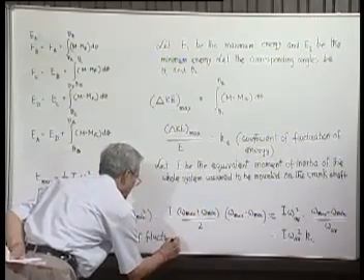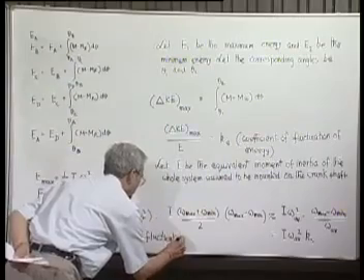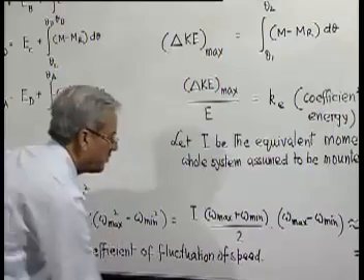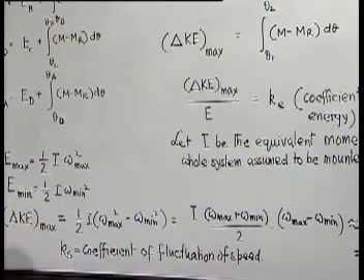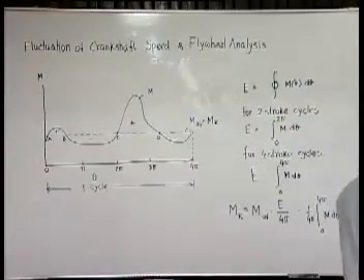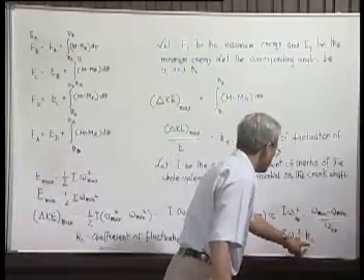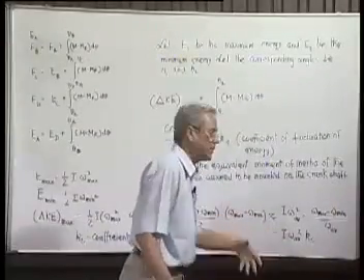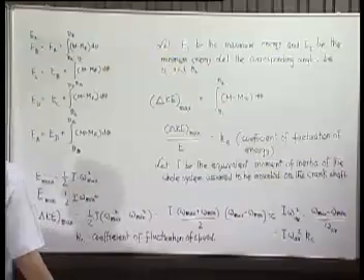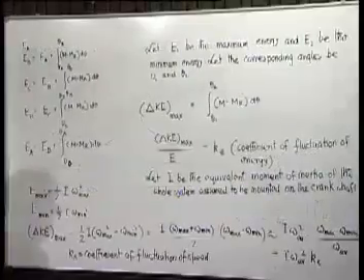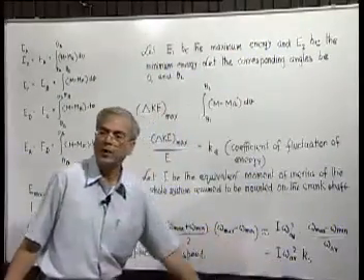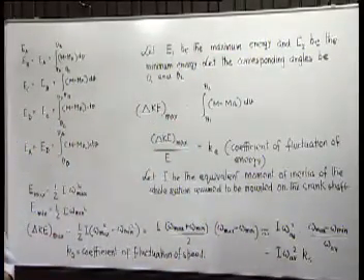This is an important parameter which has to be prescribed depending on the situation or the kind of machine we are driving with the engine. So therefore, we find that if Ks is prescribed, running speed is known, which is the design speed, and the turning moment diagram is known, then in the steady state we can find out what must be the equivalent moment of inertia of the whole system.